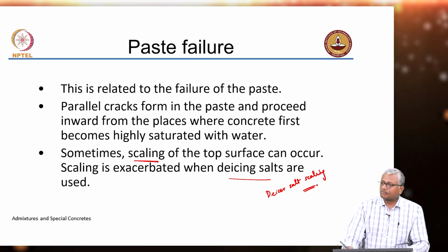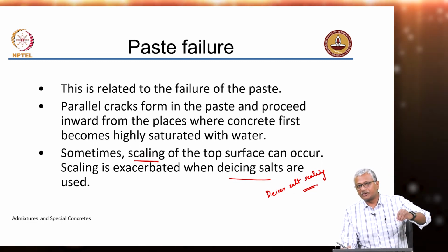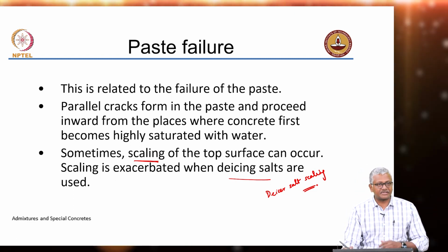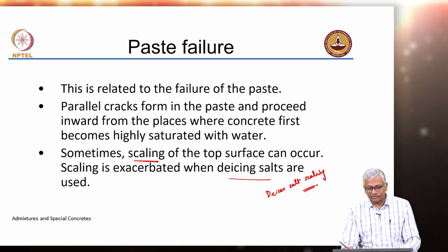The scaling due to freezing and thawing is only happening because water is getting into the pores, expanding and then failing the surface of the concrete. Okay, that is basically the paste failure that happens because of scaling.